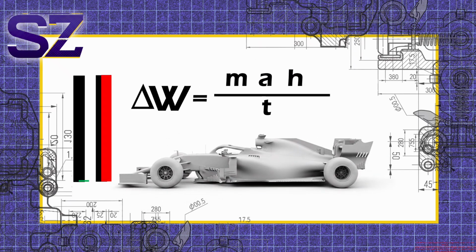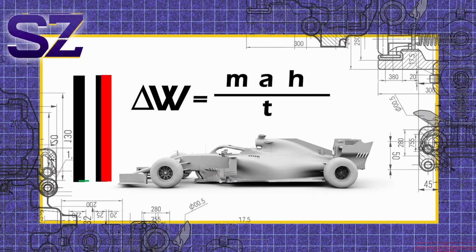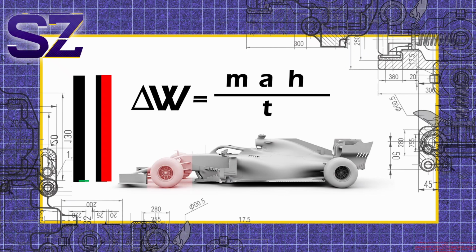The formula is change in force equals car mass times deceleration times the height of the center of gravity, all divided by the wheelbase. This load transfer puts more weight on the car's front axle, which is great for front grip, but can easily overload the tires and cause the fronts to lock up into the corner.